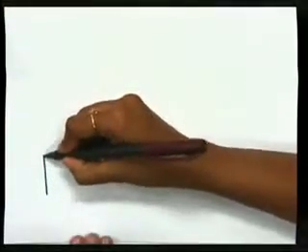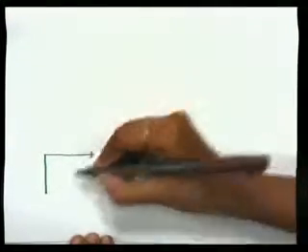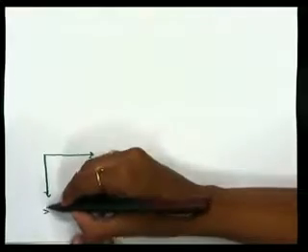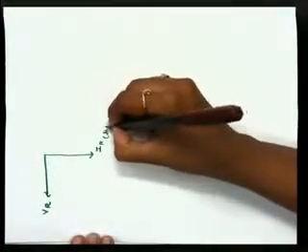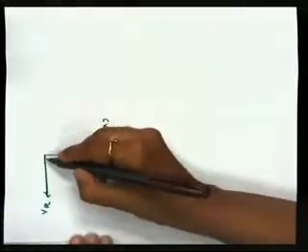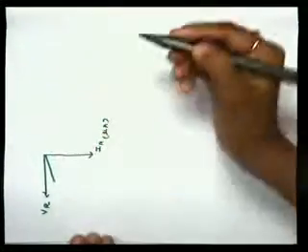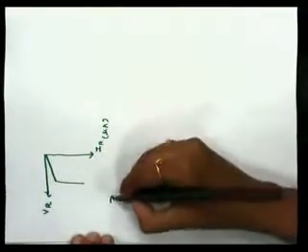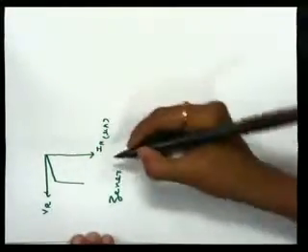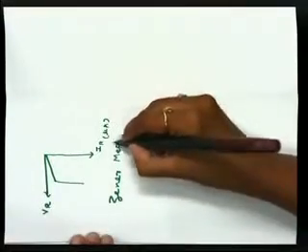In the reverse bias characteristics of the Zener breakdown, VR is the reverse bias voltage and IR, in microamperes, is the reverse bias current. This is the reverse saturation current, and this type of breakdown occurs when the Zener mechanism plays a role.